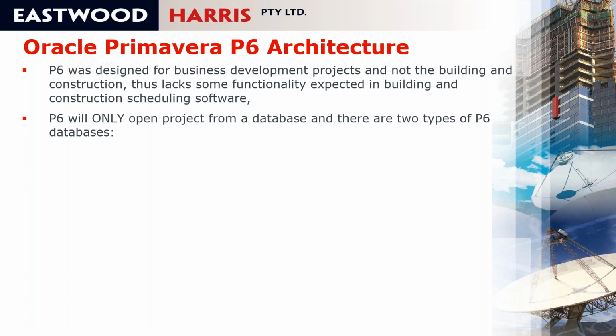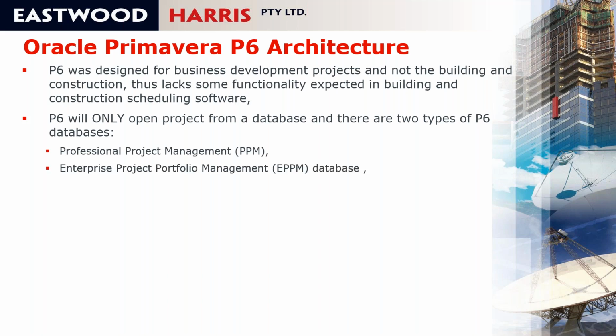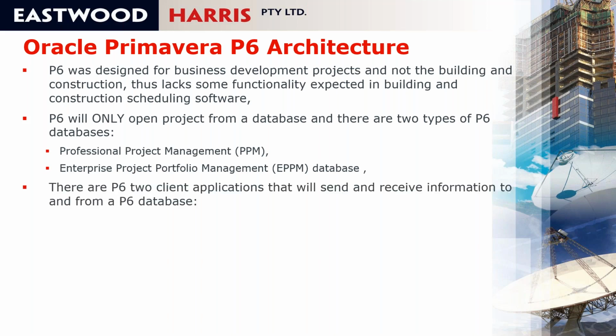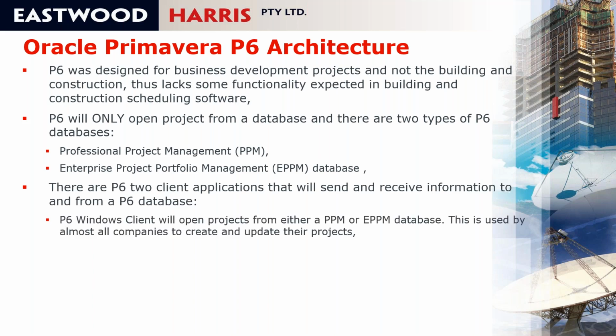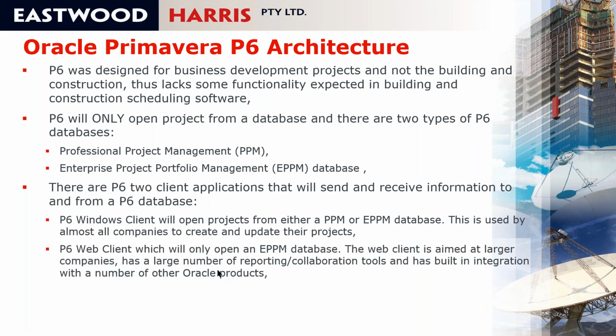So P6 will only open a project from a database, so you have to be connected to a database, and there are two types of P6 databases. There's the professional project management database and the enterprise project portfolio management database. And there are two client applications that will send and receive information from a P6 database. There's the P6 Windows client that most people use to manage projects, and that will open projects from both of these databases. Then there's the P6 web client, and that will only open up an EPPM database.